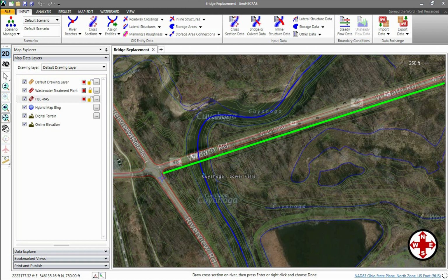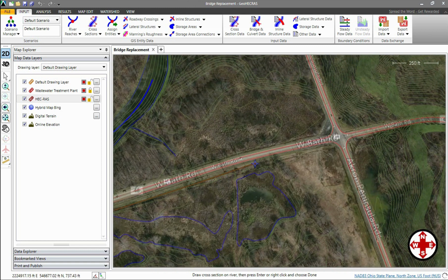As I described earlier, this cross-section is defined in the full valley region adjacent to the upstream roadway embankment. If you can see elevation contour lines, then it is much easier to determine where to place this cross-section. You can draw the cross-section from left to right, or right to left, it does not really matter. The software will figure out what you're doing. As you digitize the cross-section polyline, simply click where you want to set a pivot point or anchor point to change the direction of the cross-section polyline. When you are finished drawing the cross-section polyline, right-click and choose Done from the displayed context menu.